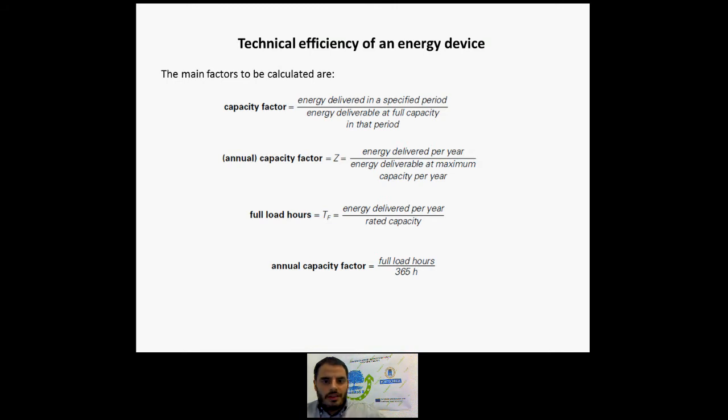But are these values of efficiency of great significance, since the inputs for renewable energy devices usually arrive without cost to the local environment as rain, wind, sunshine, and waste. If we pay for the input, for example, fossil fuel, then device efficiency is very important. But if the inputs are free, it is more important to assess the actual production of particular devices at specified sites. Moreover, the environmental inputs are very variable, so the inputs are best averaged over time, usually a year.